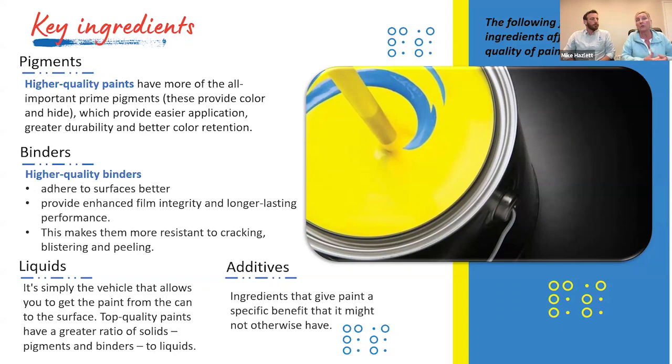If you're going through a major color change, so your building is peach or yellow, and we're going to an off-white, there's a possibility it could need two coats. Again, we would come out and determine that. We could put samples up on the wall. Your contractor could do that. So that's kind of hard to narrow down and give you a straight answer. Again, in mentioning how many coats, it's more important to recognize the paint thickness, or the mil thickness. That's what's really looked into on our behalf.